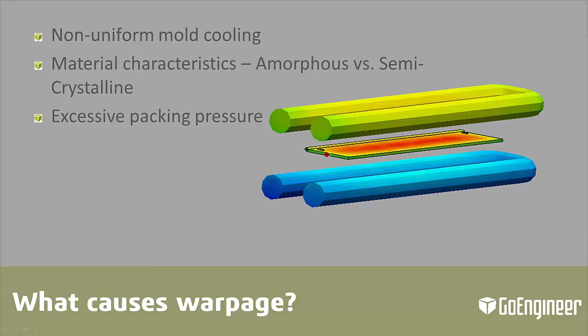With that being said, we can also have warpage caused by inadequate packing pressure. So you have a window between excessive and inadequate that you have to hit in your injection molding process to be able to control your warpage as well.